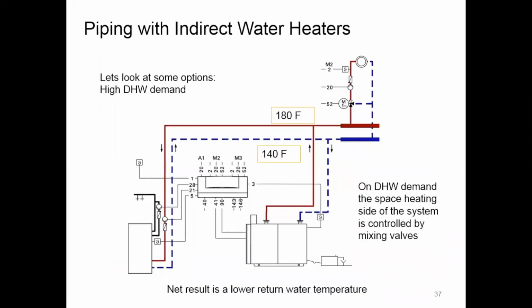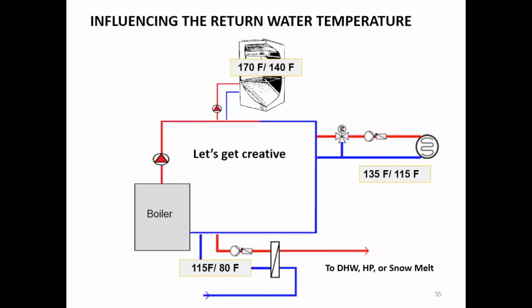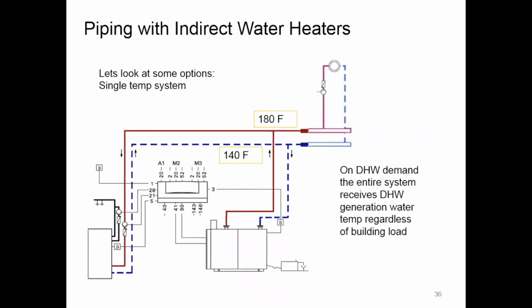Okay, yeah. So the question is, where here it says 115, the question came up, can you set domestic hot water 115? Typically, when it shows domestic hot water there, that's actually domestic hot water preheat, a lot of times what we'll do there. So yeah, I see the confusion with the 115 and the domestic hot water. It's not actually for the generation of the hot water, it's to preheat the hot water before it gets to the hot water heater.